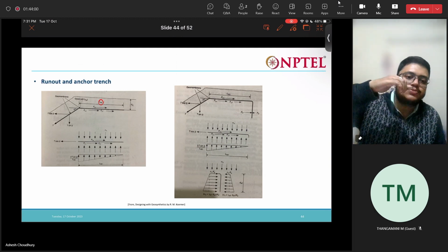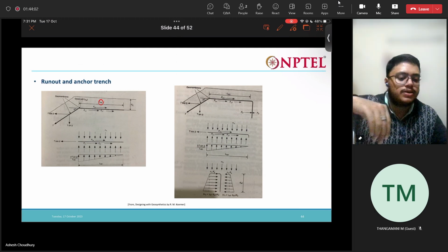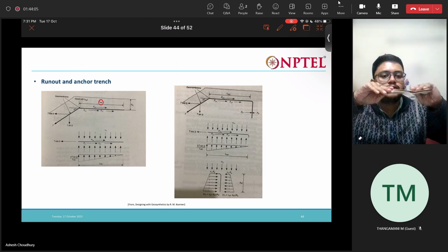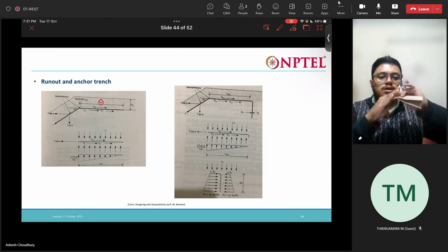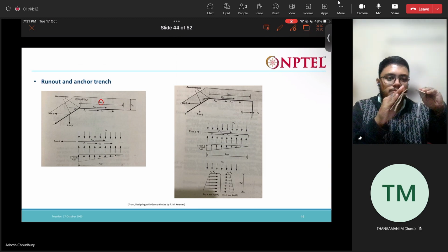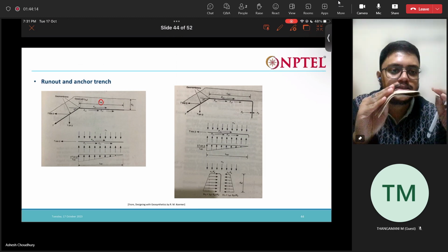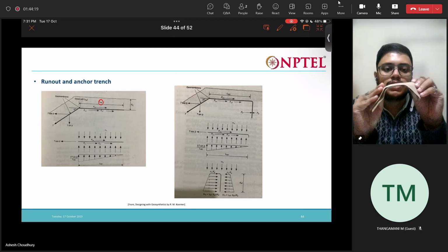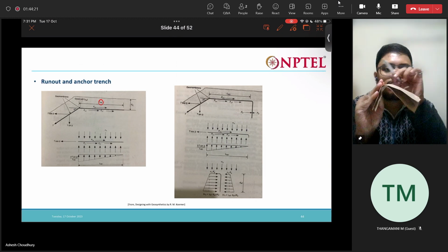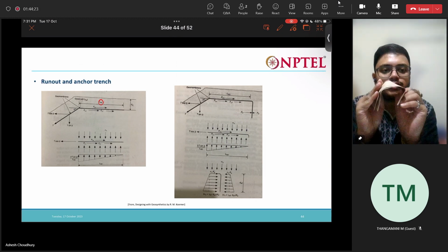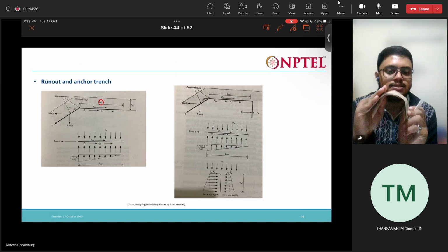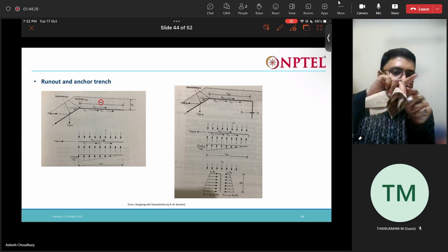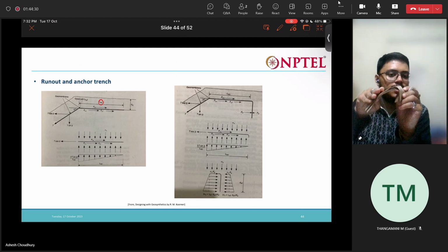The other thing which is possible is that we can anchor the geomembrane. So we place the geomembrane. This is slope, this is straight. Slope, then straight, and above this we are placing soil cover, and this portion we can anchor into a trench, and then fill the trench with soil, so we can anchor it. We can anchor this portion into the soil.